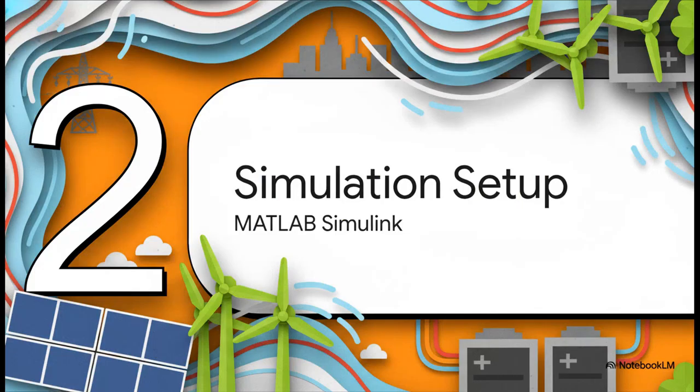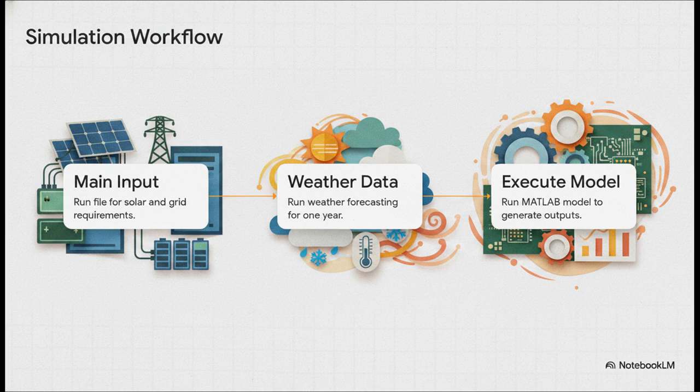All right, moving on to Section 2, Step-by-Step Simulation Setup. Let's look at executing the MATLAB Simulink environment. Listen, if you're replicating this simulation yourself, you must follow this exact sequence. You can't just smash the Run button. Step 1, you've got to initialize your main input file. That loads all your structural parameters like the parallel connected strings for your solar arrays and your baseline grid requirements.